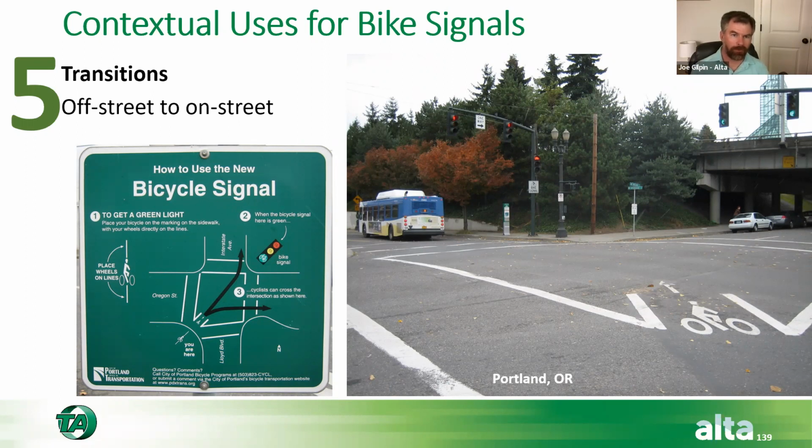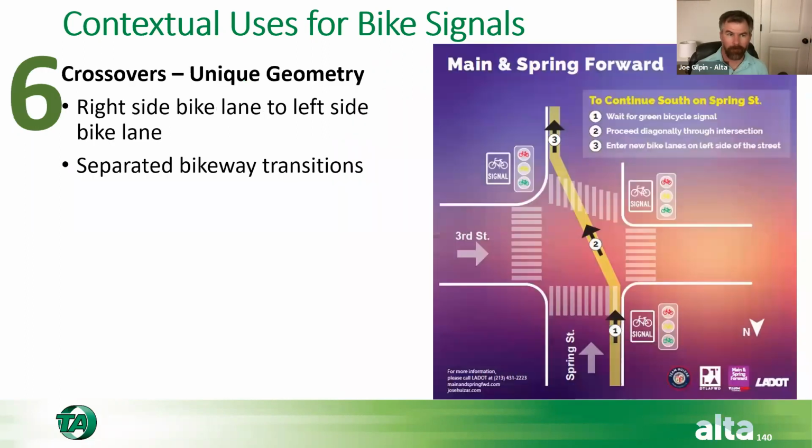So the Synchro model typically will tell you the worst case scenario, and then you have to use some level of judgment to say, okay, if this is only happening occasionally or once out of every so many cycles during the peak, what's that actually going to do to our performance? Because it'll probably be somewhere between the existing level of performance and the worst case that's being shown. But it's never going to be as bad as what Synchro actually says. So neat little tidbit of information there.